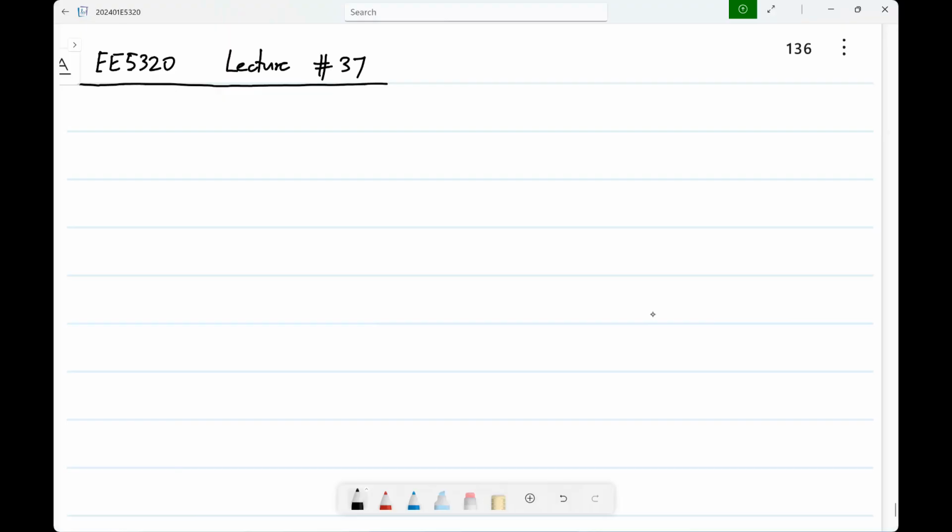It's another feedback circuit. A fully differential circuit has two inputs and two outputs, whereas a single-ended feedback circuit has one input and one output. So you have two feedback loops, but you don't think of them independently for two inputs and outputs, but for the differential mode and the common mode. The differential mode defines the functionality. The common mode typically sets the bias value.